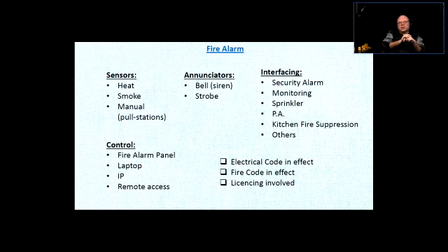The wet sprinkler system means that in the pipes, because it's kind of a plumbing system, all right? So there are a bunch of pipes along the building, and out of those pipes there are sprinkler heads, all right? And the sprinkler heads have sensors. Usually when there's heat there, the sensor gets melted and it triggers that particular sprinkler. Usually it's the only one that's triggering. It's not like in the movies that you break one of them and the whole system goes off. Yes, it's a possibility.